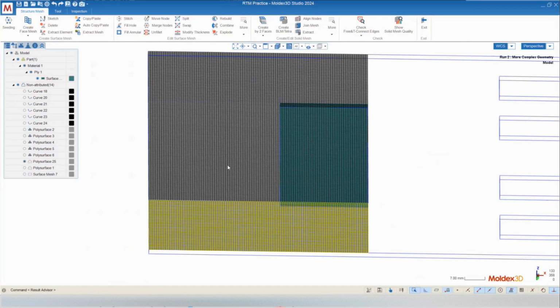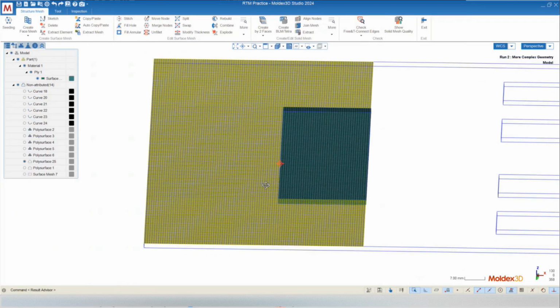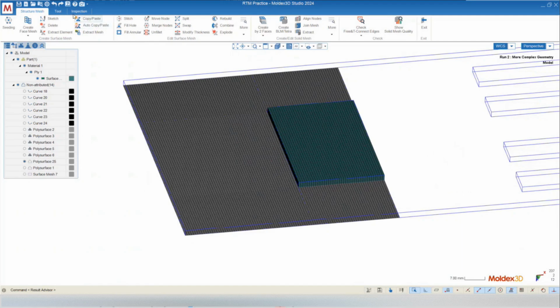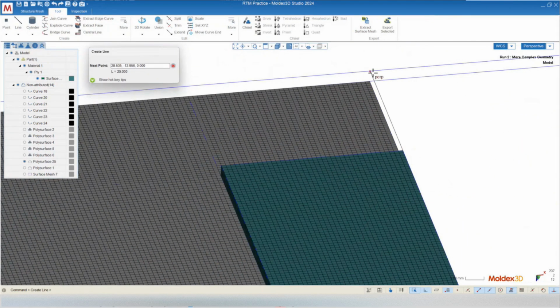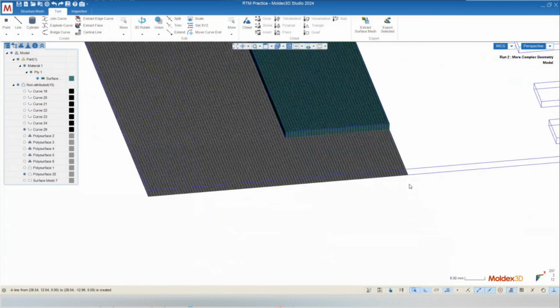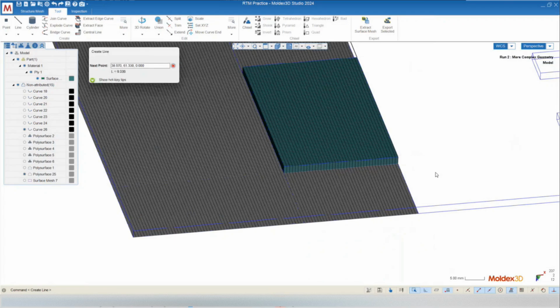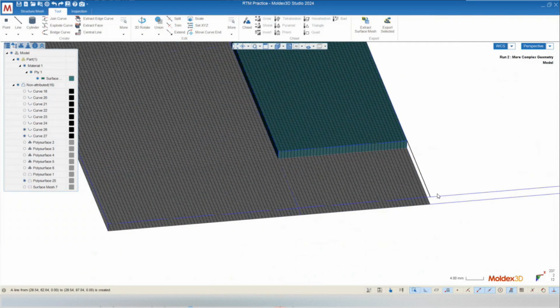So we have 5 blocks of mesh. We can just consider this as one continuous mesh. And actually, we will eventually merge all of these meshes together. So actually, instead of creating all of the feature lines that we did before, we're only going to create 2. I'm going to go to the Tool tab, Line, and we'll go from here, perpendicular on the bottom surface here. We'll go from this corner perpendicular, and from, show it with that mesh snap, this corner perpendicular.